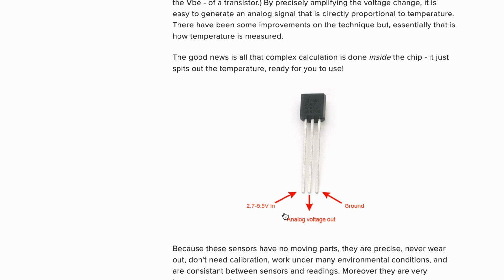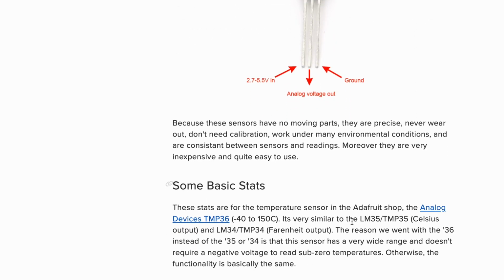So when you are building an IoT device, you have to do a small dive into what outputs it is going to give. For example, this one is going to give out raw data, an analog voltage output, which means the temperature is going to come out as a difference in voltage. Also it would be analog. So this is the part of data that needs to be processed in the embedded system itself.